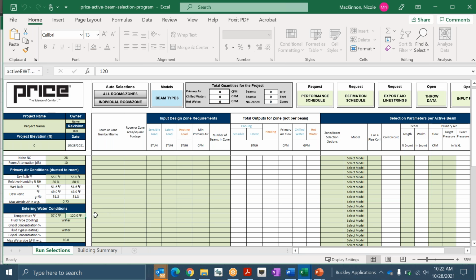It's not going to be the same as a fan coil system, which is much lower. So that is a point you want to make sure your facilities team understands, so they don't come in after you design the system and commission and drop that water temperature down below the space dew point. We'll hit that a few times today, but that's definitely something you want to understand about this system.